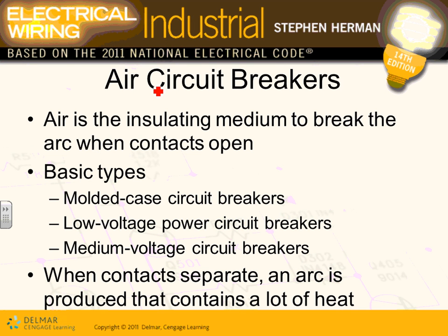Okay, air circuit breakers. So that's how that tripping is. The tripping mechanism in any circuit breaker, we talked about thermal, we talked about magnetic. There's also electronic, guys, where you can sense the current electronically and make a decision. That's called electronic circuit breakers. Adam, you're looking at a thermal circuit breaker right here, and the circuit breaker right at the top of it, guys, right here, is actually an electronic circuit breaker. Can you see that adjustable? This electronic circuit breaker, you can adjust it. So electromagnetic, thermomagnetic circuit breakers, and electronic circuit breakers.